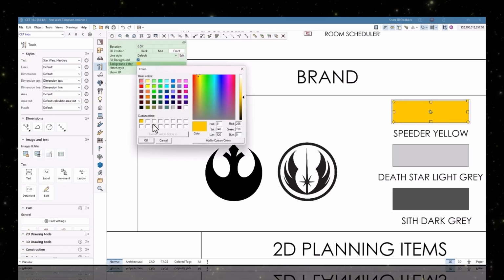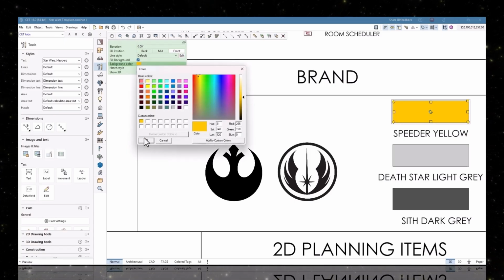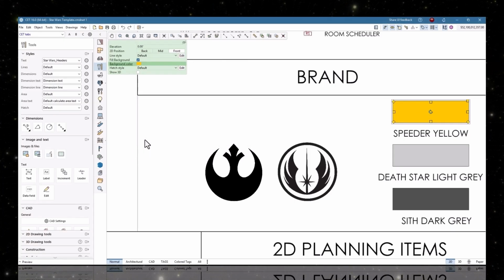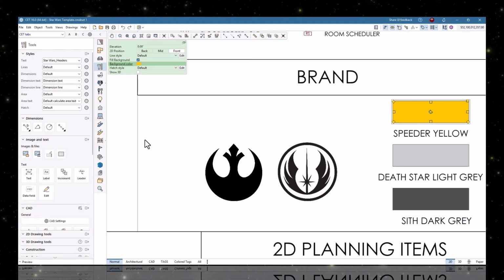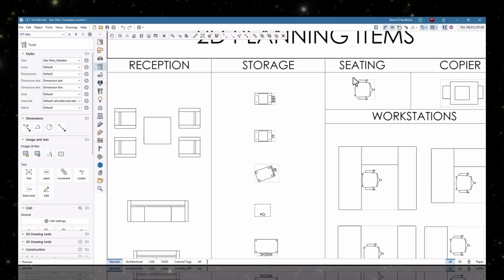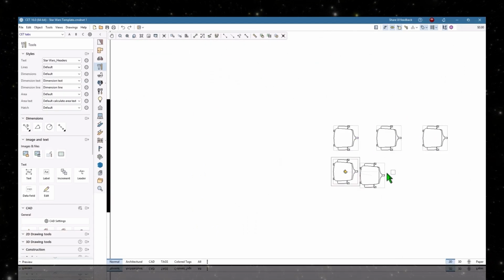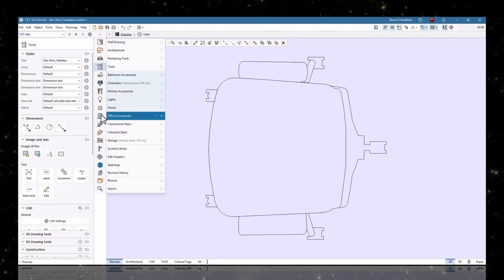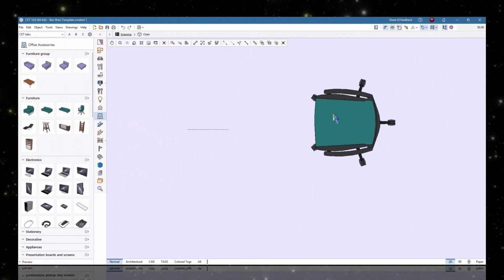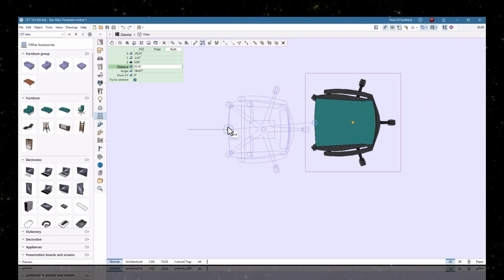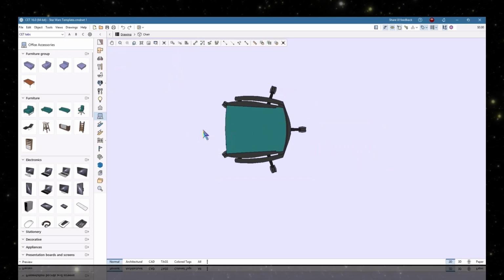These items that exist in this 2D toolbox should be generic and be able to be used on multiple different projects. They're used to house department standards. The 2D blocks here are always nice to have on hand to do some quick space planning if you don't know what furniture or items that you're going to use. Then you just replace the 2D symbol with your 3D item, and now your project has already been planned.